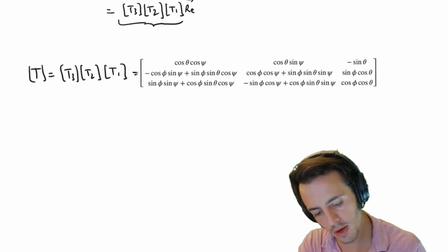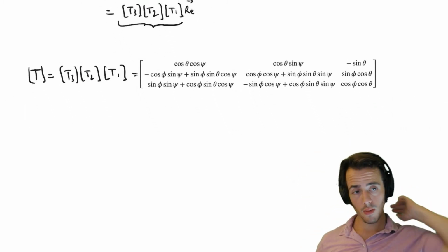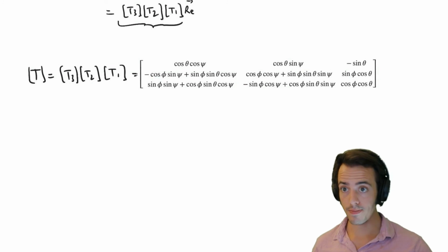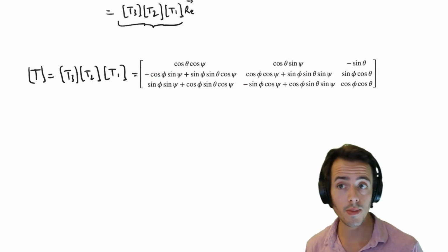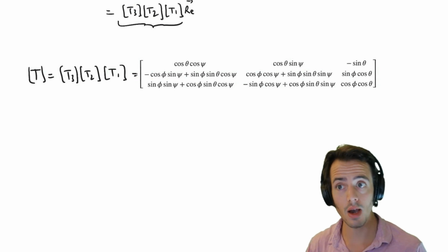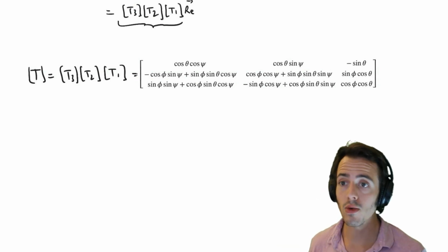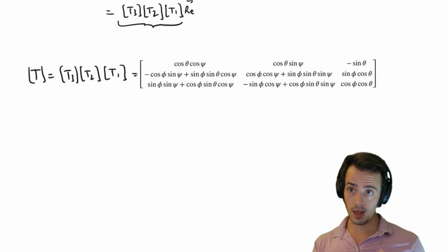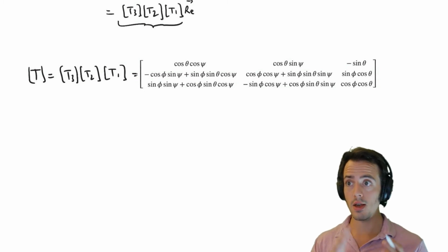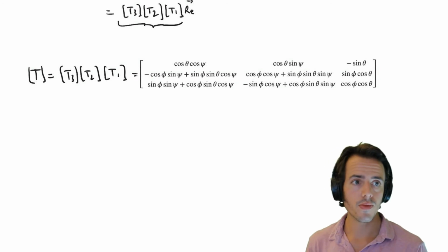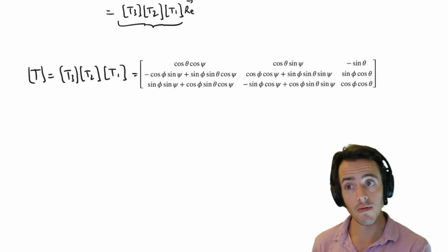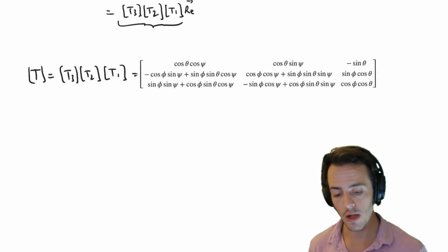And what this enables us to do is take quantities from one axis and put them into the other. Okay, we're going to use this quite a bit in this course, for later parts to convert between, say, quantities like the velocities in body axes and Earth axes. We're going to use it mainly to convert the gravity vector, or the gravitational force.